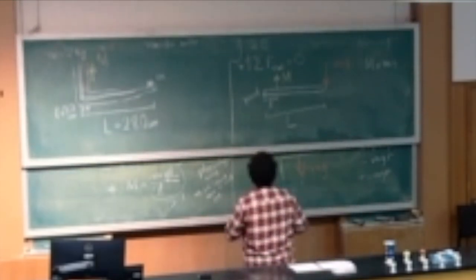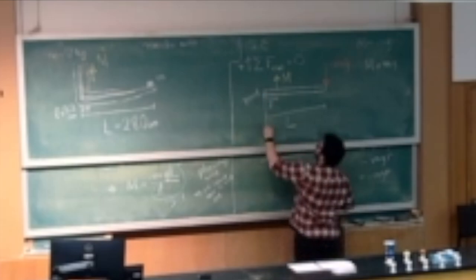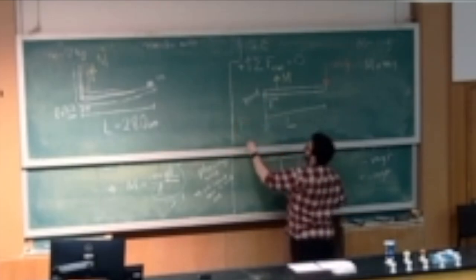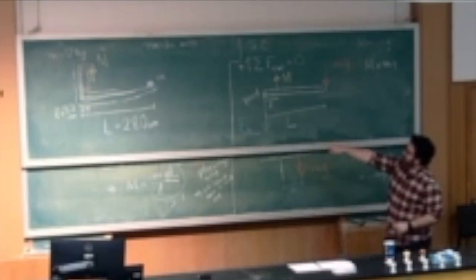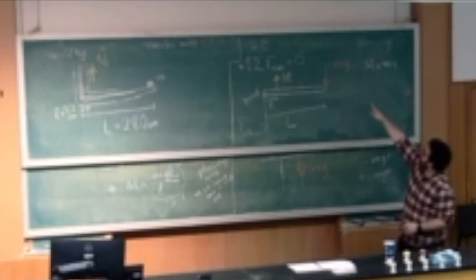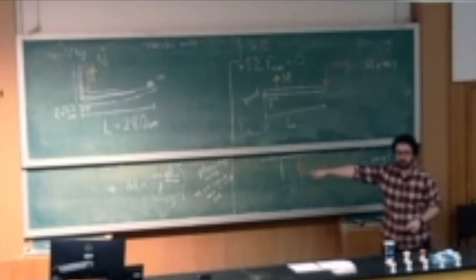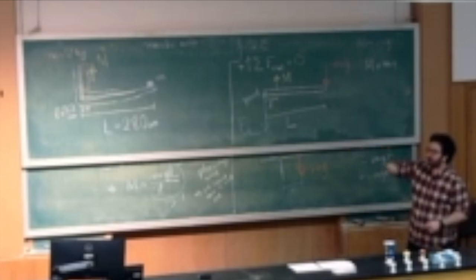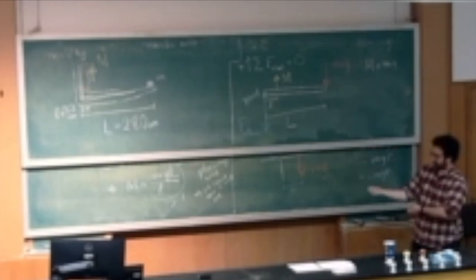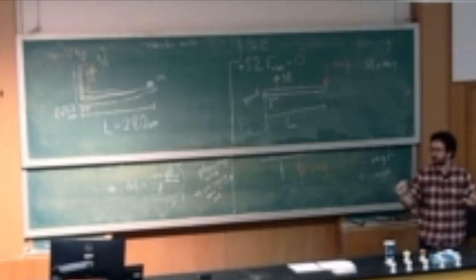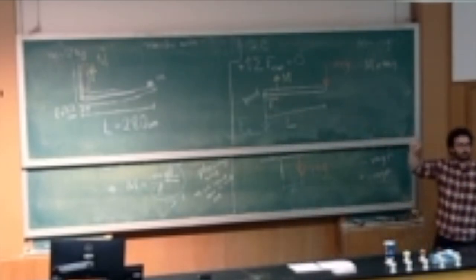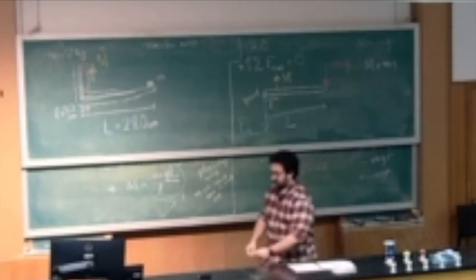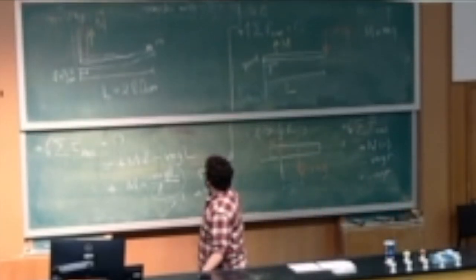So we have this guy missing in the first place. Let's call it F elbow. Exactly. Now you go to the force equation with this condition, and you can compute the force that develops in your elbow. Nice and easy. And since this force goes through the pivot point, it will not disturb your rotational equilibrium.